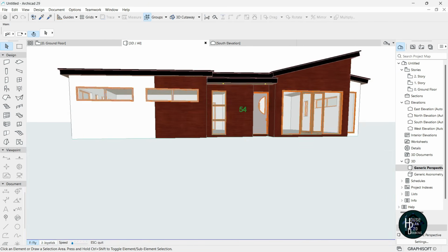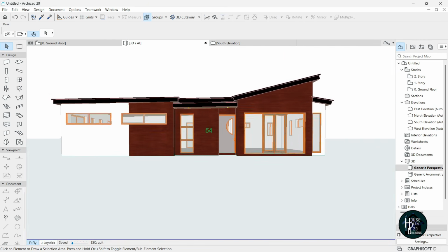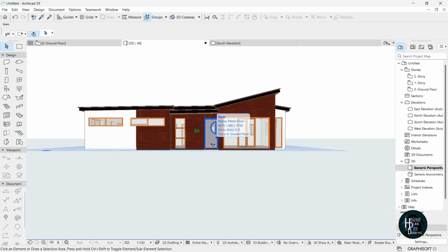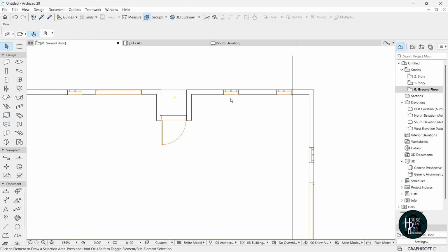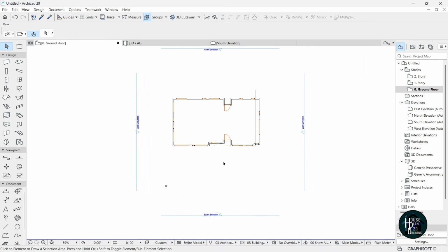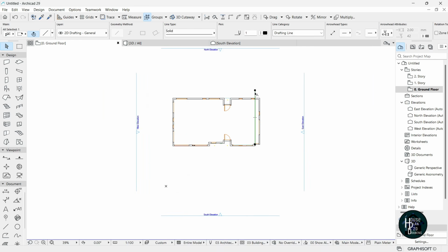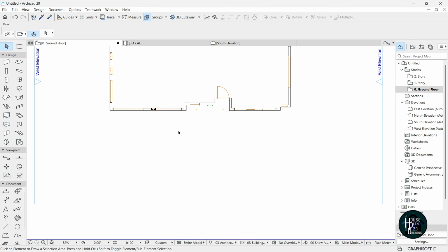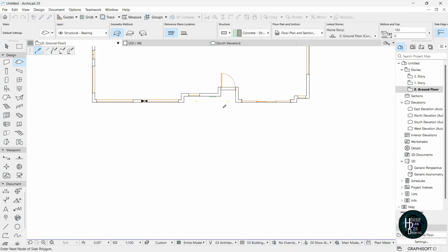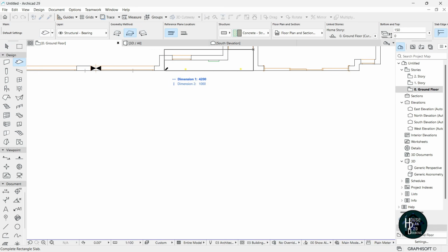Okay, now we are done with this particular 3D model. I'm just going to work a little bit on the landscape features. I'm just going to go to the ground floor plan, and then I'm just going to go and set something up real quick. Okay, so I'm just going to click this line, delete the line for now. Then I'm going to hold on Alt, select this, then I'm just going to click like so, click on the square, on this rectangle rather, put a cursor here, allow it to load up. Okay, then just give it distance or maybe something around here.